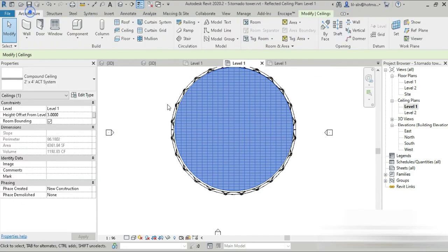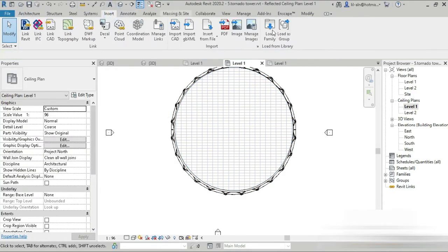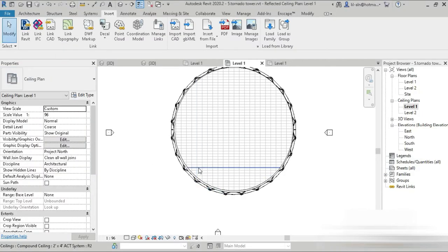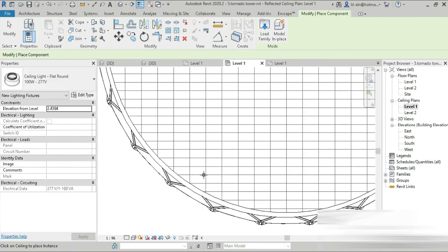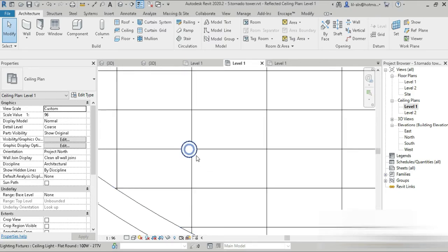And left, fine. And the height of it, let's keep it as 3. And you know what? Let's even add a light, isn't it? Ceiling lights. So components, and okay, this is the ceiling light that we just imported. So how about we paste this right here, and automatically it became part of our ceiling.